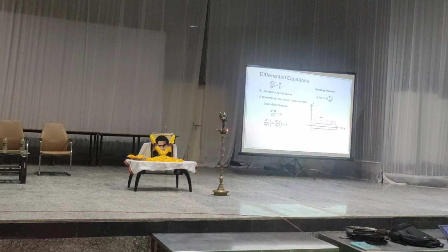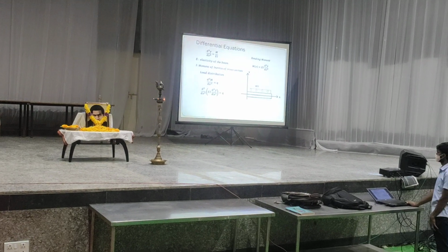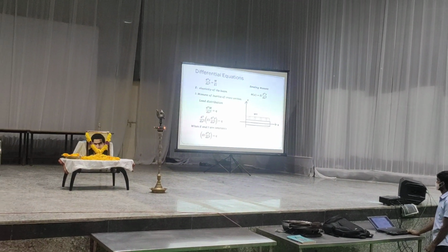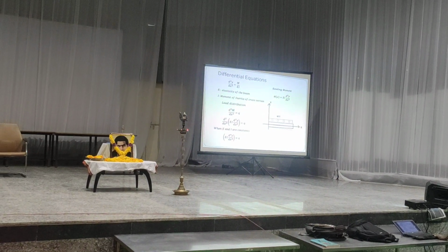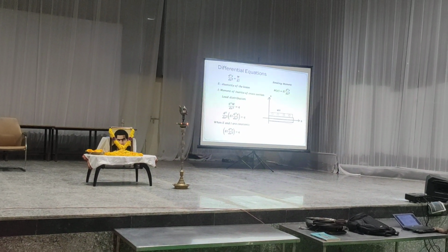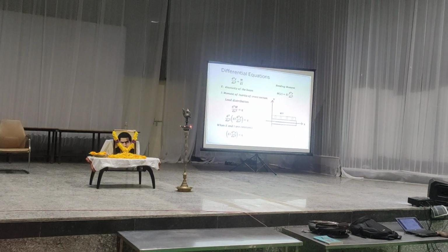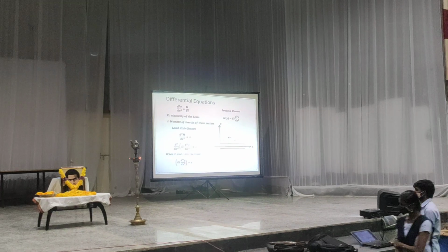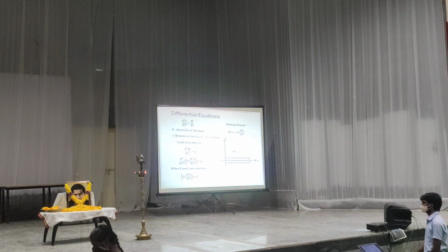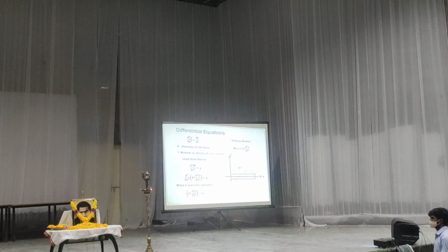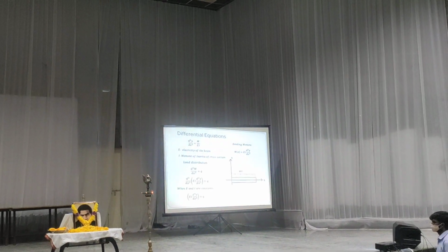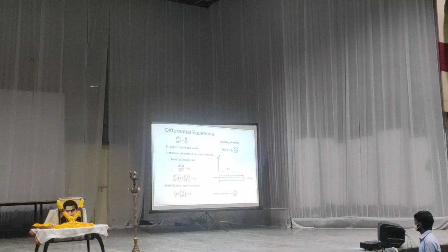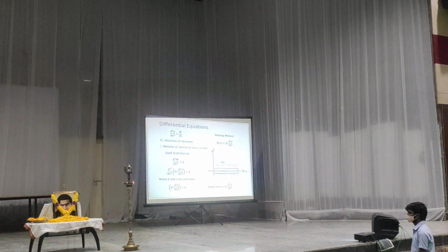That load distribution will be equal to the second derivative of the bending moment. So when you know that this E and I are constants, then it will become a fourth order differential equation. So now you need to know the solution of this fourth order differential equation. Of course, this equation is easy to solve. How do you solve it? On the right hand side you only have a function of x. If you just integrate 4 times, you are going to get y. Next. And that is the formula for shear force. Next one.